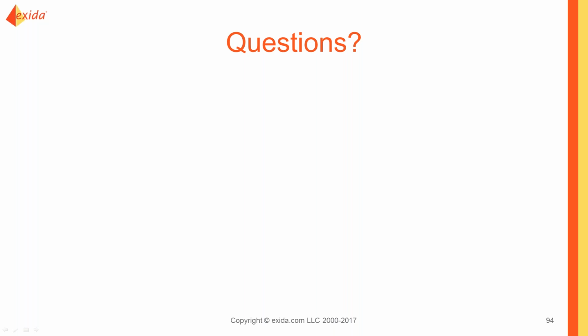Just from human reliability, when there's stress, there are lots of studies, and that could be a whole different webinar, but on human reliability analysis, you still may want the push button there for the operator to use if they needed it, but you wouldn't typically give it credit because they wouldn't have time, they'd be under duress, so the reliability of the operator would be low. So in that instance, you probably wouldn't give it any credit.